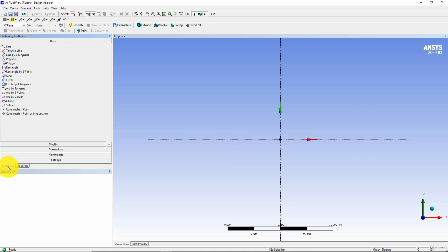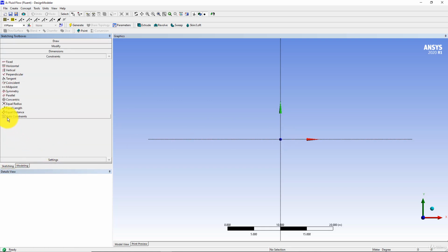And then go to sketching mode, and from sketching mode choose circle, and when you click on or hover over this origin point, this will show you the symbol P. If not, then you have to go to the constraints, and from constraints click on auto constraint, and make sure that the global and cursor are tick marked. If not, then do it.